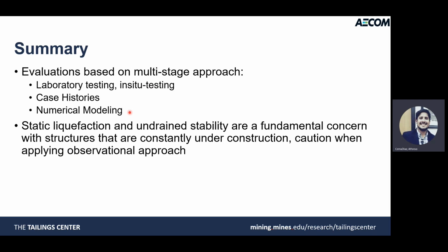As a last comment, static liquefaction and undrained stability are a fundamental concern with this type of structure, especially if we have a brittle type of behavior. So really, it's very difficult to monitor these dams against failure. So you should assume that any triggering mechanism will happen, and be careful with your observational approach, because that won't work in this type of dam that has these brittle materials.